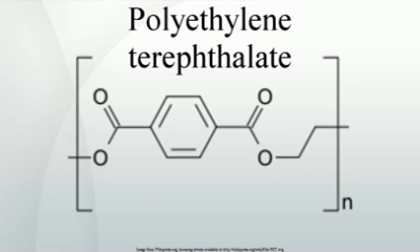For the adjustment of the necessary viscosity, besides an efficient drying of the flakes, it is possibly necessary to also reconstitute the viscosity through polycondensation in the melt phase or solid-state polycondensation of the flakes. The latest PET flake conversion processes are applying twin screw extruders, multi-screw extruders or multi-rotation systems and coincidental vacuum degassing to remove moisture and avoid flake pre-drying. These processes allow the conversion of undried PET flakes without substantial viscosity decrease caused by hydrolysis.